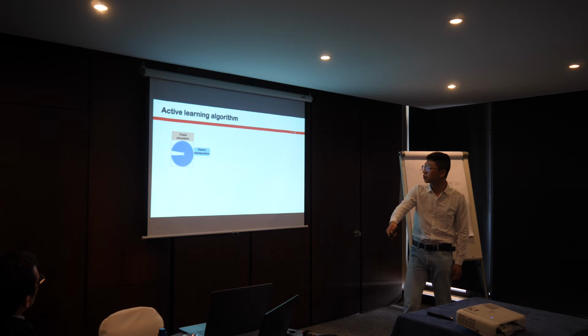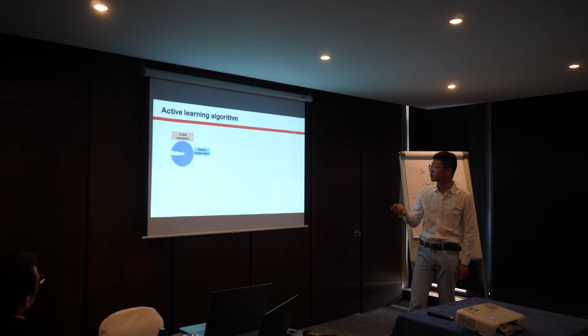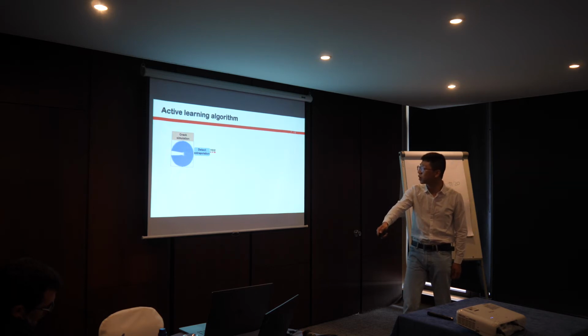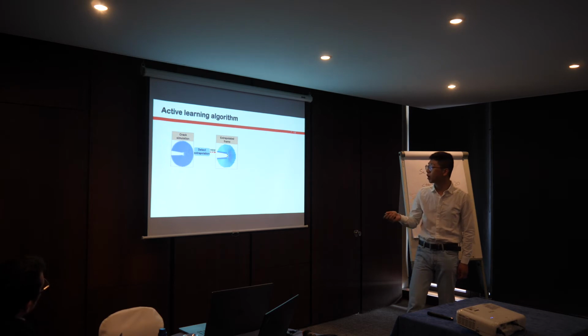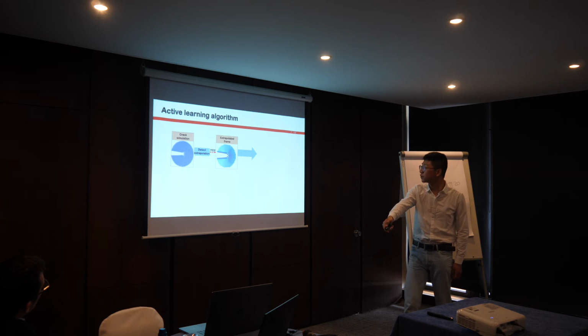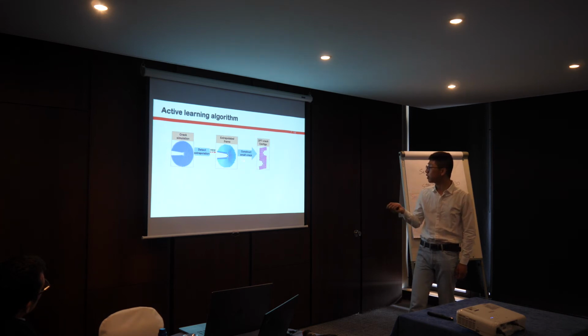We set a threshold for this error. If the error of any atom goes beyond this preset threshold, we stop the simulation, take out that frame, the frame that is trying to extrapolate, and construct a small DFT cell containing the local atomic information.